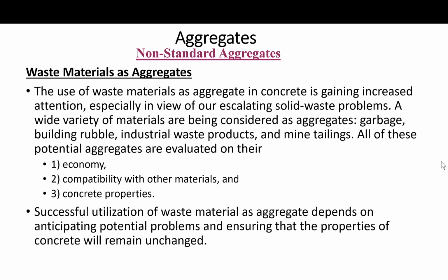Okay, so also we can use waste materials as aggregates. So basically the use of waste materials as aggregate in concrete is gaining increased attention, especially in view of our escalating solid waste problems. A wide variety of materials are being considered as aggregates: garbage, building rubble, industrial waste products, and the mine tailings. All of these potential aggregates should be evaluated on their economy, compatibility with other materials, and concrete properties. So successful utilization of waste material as aggregate depends on anticipating potential problems and ensuring that the properties of the concrete will remain unchanged.